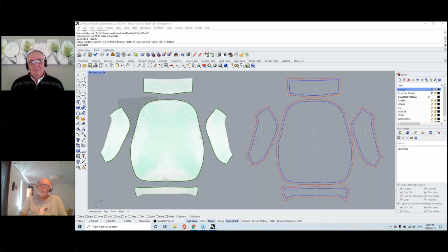If you were to scan a yacht, starting from the rear and going clockwise around it, you'd have a good chance of having a scan path of 20 meters at least. Now, the volumetric error is, I believe, 0.25 millimeters per meter of path.